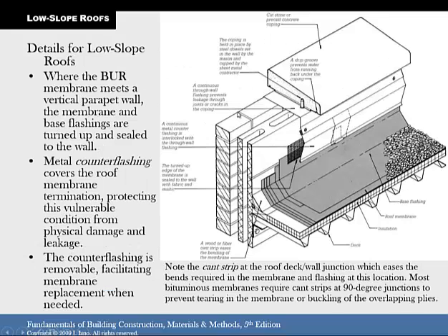Here's a roof parapet wall that's on your flat roof, and you can see that the roofing membrane goes up the wall and then under all of this flashing. And then you got your roof gravel over here, and this roof probably has a drain out here in the middle somewhere that it's going to slope towards. And that's called counter flashing when the metal counter flashing covers the roof membrane. So this flashing comes up, loops into there, goes under there, and that flashing overlaps that, goes up there.